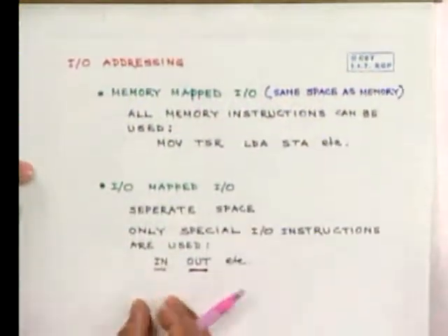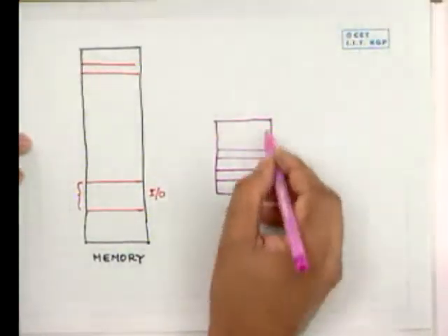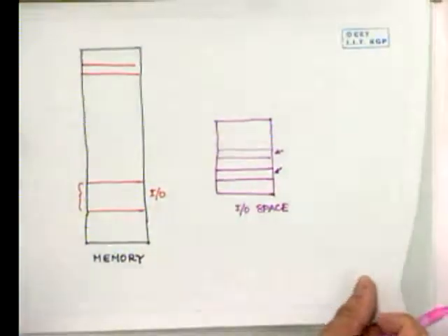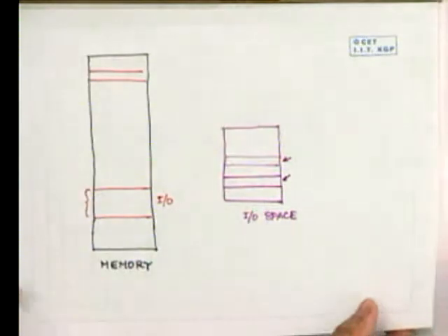In that case, we are mapped automatically onto the I/O space. Now, one can choose memory mapped or I/O mapped I/O whenever I/O devices are being interfaced. It is up to the designer to choose whether to use I/O mapped I/O or memory mapped I/O.